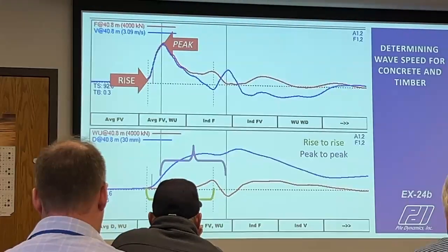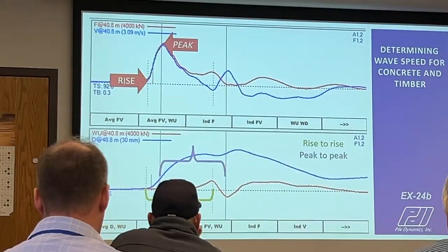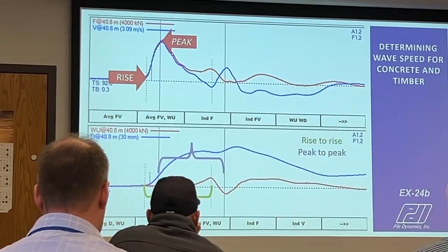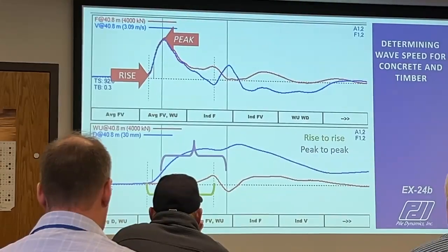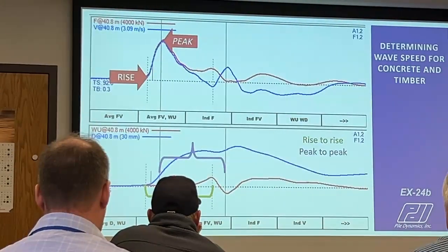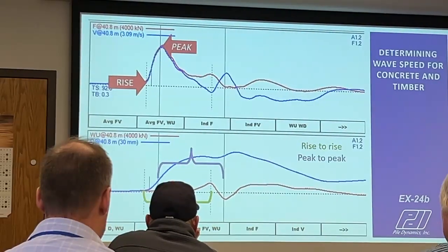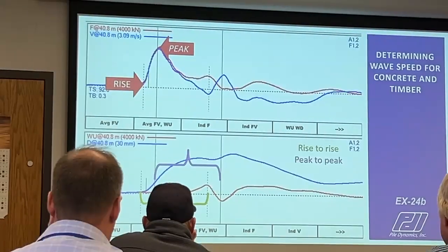Wave up is the accumulation of resistance over time or with depth. And so this is telling us that we have very little resistance in the upper 2/3 and then considerably more down in the bottom. Our force drops, our velocity increases, so the pile toe moves, and then things go back to 0.